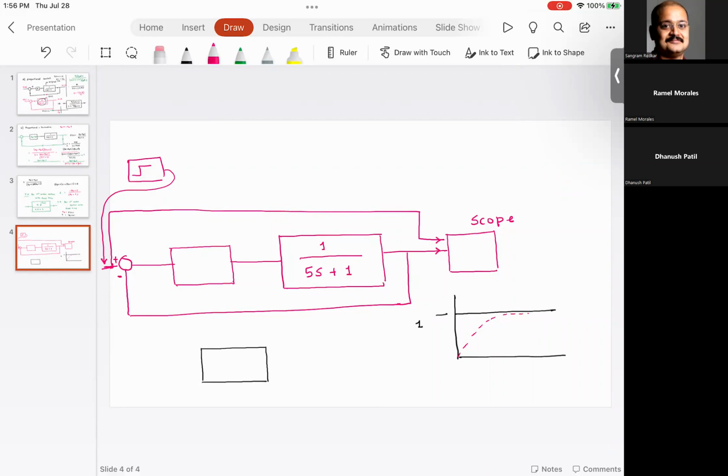And that steady state error is when the value of time becomes infinite. So what you should do is, if you substitute the value of s equal to infinity, that is what is indicated as the steady state error. And we will look at that. The only point here I want you to understand is that with proportional control, you add the gain, you will still have some type of steady state error.